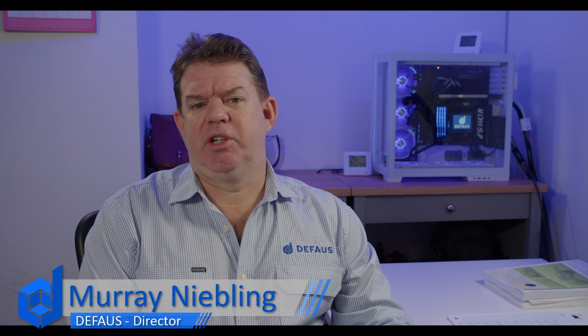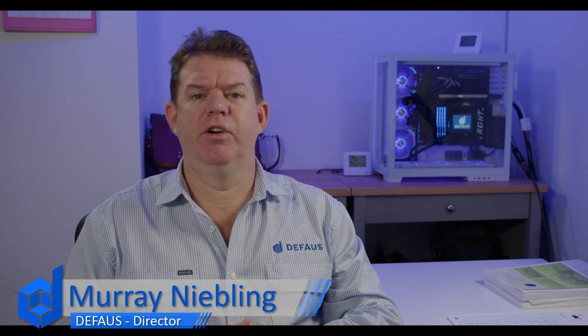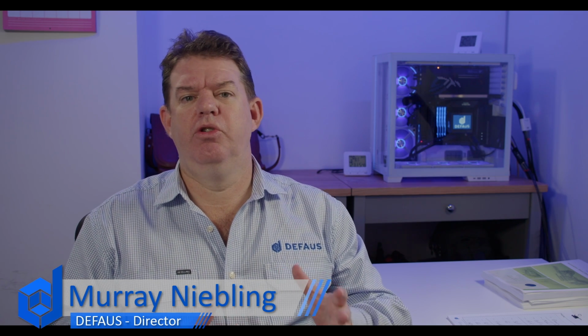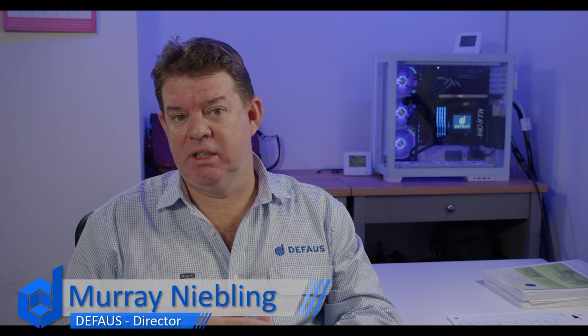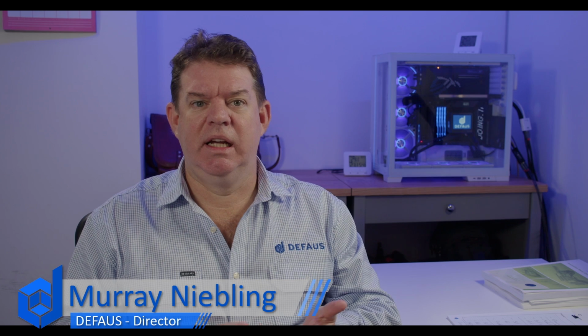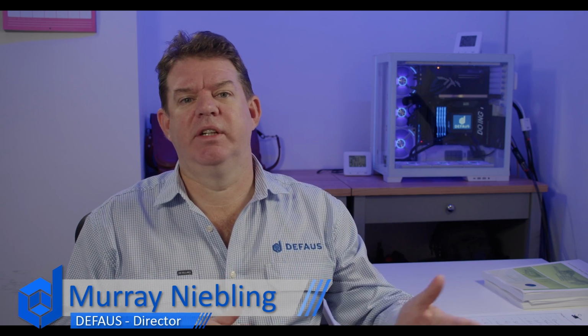What I will demonstrate today is our workflow to produce these two separate sets once the design model has been completed. I will first run through our new SysDef custom drawing processes palette, create and export a material summary list, a bolt and anchor list, and a purlin takeoff, followed by the creation of the engineering set and then the fabrication set. Once those sets are created, I will then create a full set of PDFs for us to review.